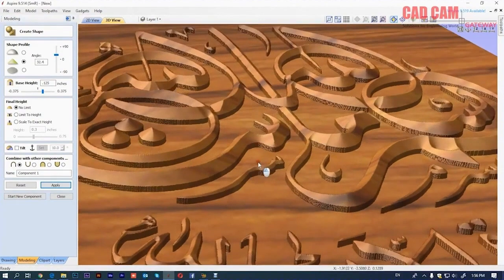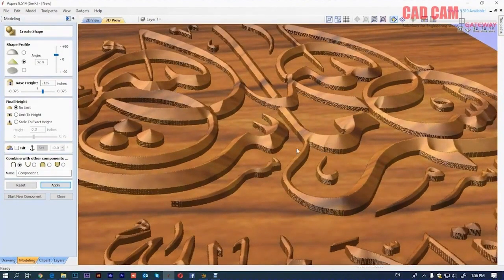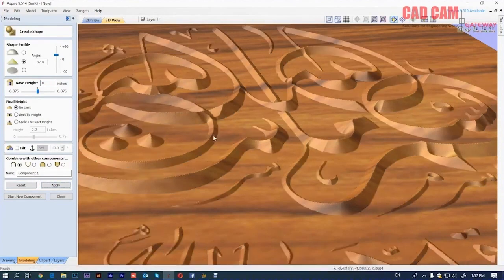Look here. This area that you can see, pay attention to this area. You can increase or decrease its height. I'm setting it to 0 here. When you set it to 0 and apply it, you'll see that the base connected underneath it will become 0. Just like we set its base height to 0 here, you can see it right in front of you. Now if I set it to 0.05 and apply it, you'll see all the effects appear right before you.